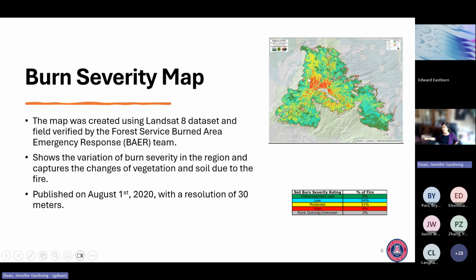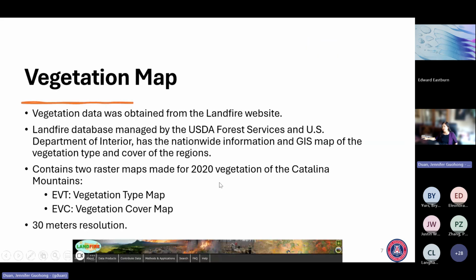In fact, we want to know, immediately after a fire, how much runoff increases if there is a rainfall event immediately post-fire. It is a flooding concern. So what we did in our study: when an engineering company does this kind of study, they usually assume the vegetation is burned down, so the CN is going to increase. The question is how much increase? Are we going to increase it by 5, by 10, and where? Those are questions for which we don't have a scientific basis.